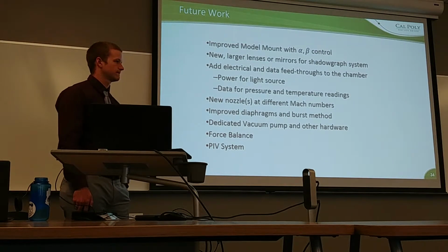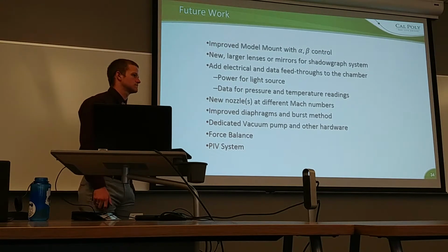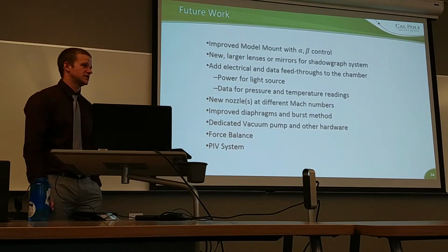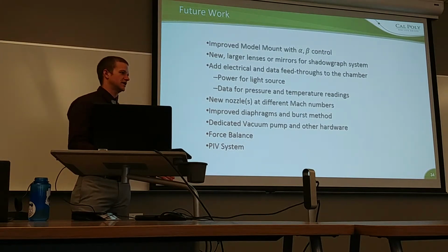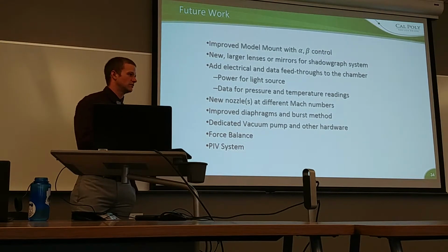Ignoring all the other things, where you have the reflected shocks and the diaphragm issues and whatnot, does the Mach number of the flow in the test section change as the pressure of the chamber comes back up to be equal? It does not change until the pressure in the chamber exceeds the exit pressure of the flow.